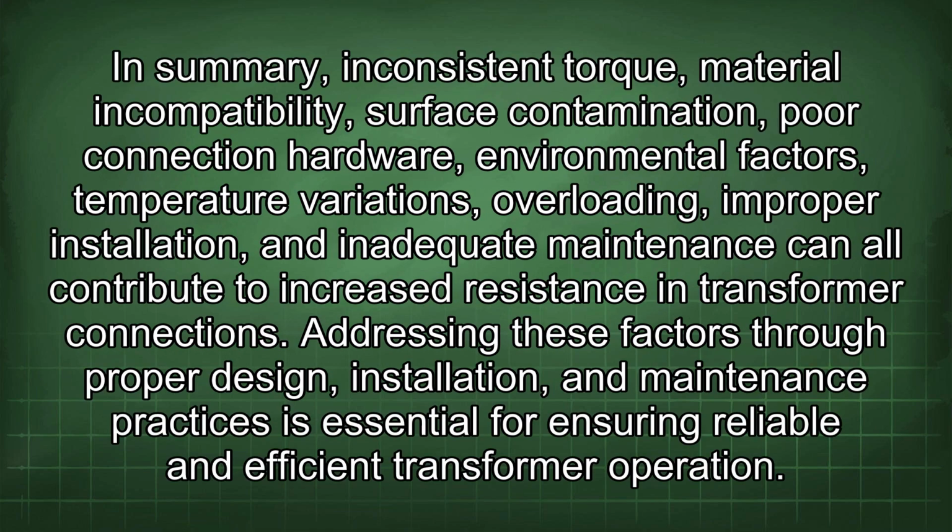In summary, inconsistent torque, material incompatibility, surface contamination, poor connection hardware, environmental factors, temperature variations, overloading, improper installation, and inadequate maintenance can all contribute to increased resistance in transformer connections. Addressing these factors through proper design, installation, and maintenance practices is essential for ensuring reliable and efficient transformer operation.